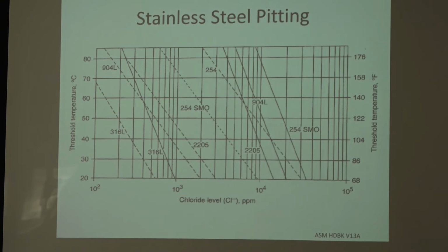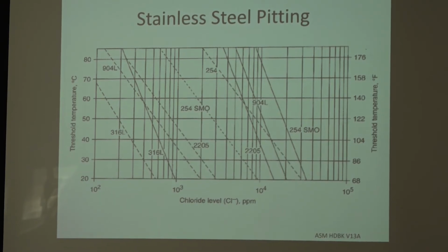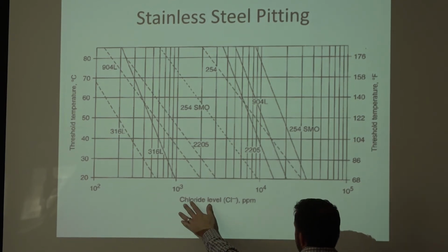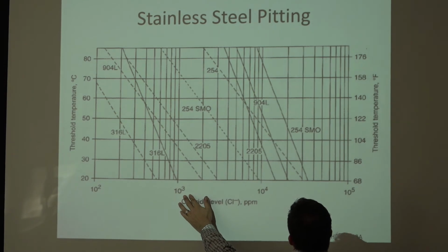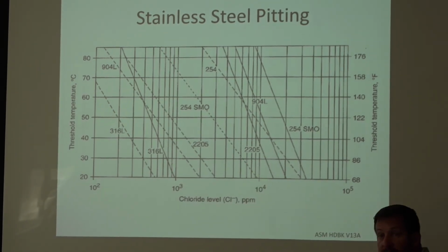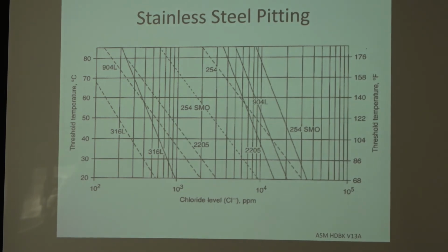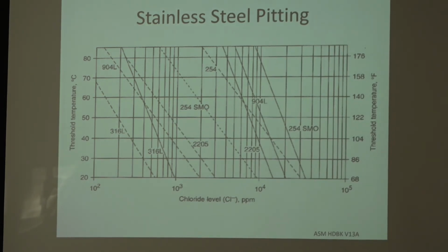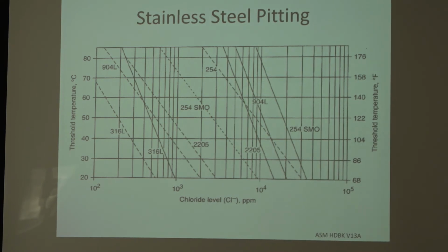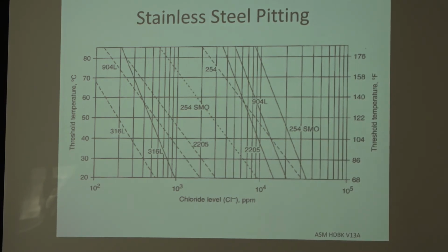The first one here in the series is stainless steel 316. That is a bit of a default if you know you're going to have an environment with a little bit of chlorides, not a whole lot of chloride. But you can see in this chart that you can increase the ability to take chlorides by an order of magnitude when you change your grade of stainless steel. And that's really where it's significant. So we can be here, you and I, complaining that stainless steel is not perfect, but if I have something to build that's not that big, and I am able to afford greater alloying content in my stainless steel, then I don't have to worry about it.